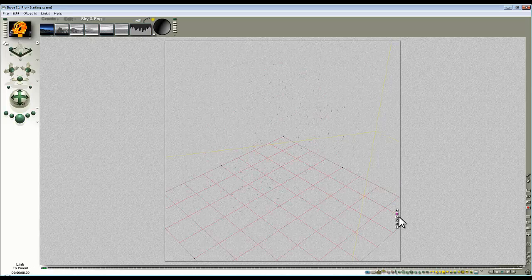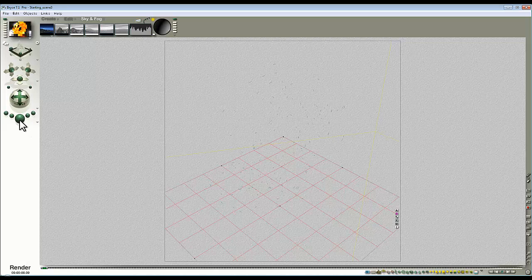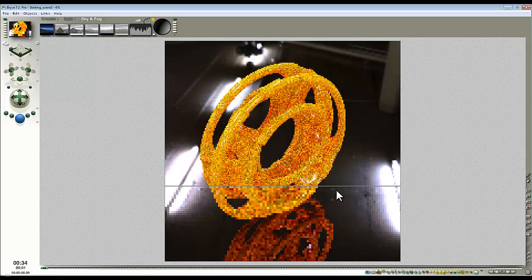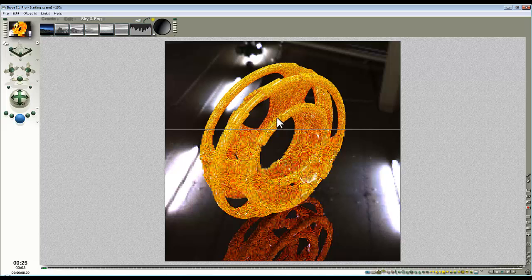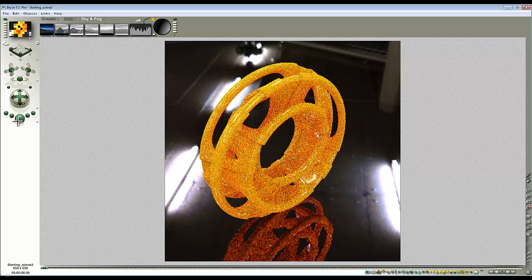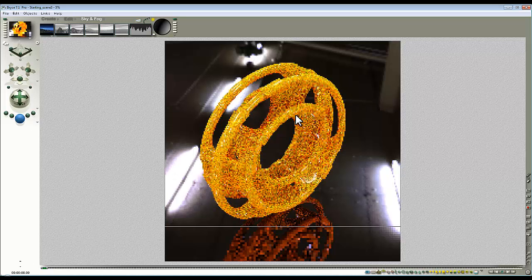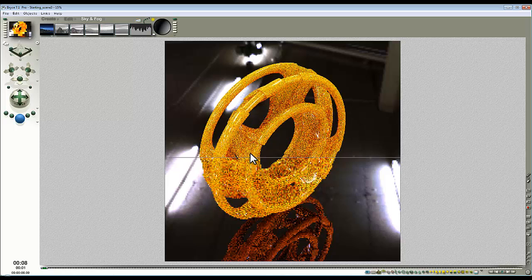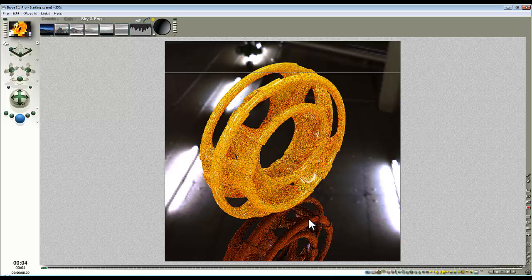I think I shall take the reflection up on the plane. Let's try 50 in there, and if I set that up slightly, I'll give it some colour. There we go. So I've got a bit of interaction on the ground from the lighting, and this has got the hue shifting. At this point it might be worth just experimenting to see what effect reducing the rays down has, so it'll just do a bit of interaction with the ground there.